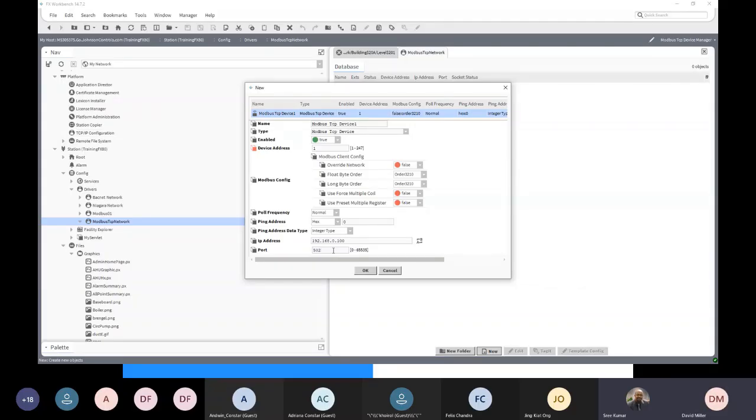David, what if the Modbus IP slave device is in a different network? Can we use the second network port of the FX80 to be configured for that, or do we need another way? Yeah, so you've got two IP ports on the FX80, and that allows you to connect to two separate IP networks that are completely different.